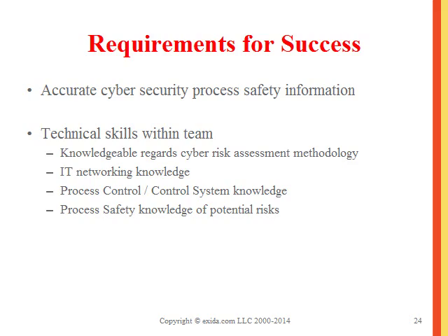So how do we make sure that we're successful in this exercise? You need good information about the process, your cybersecurity process safety information. You need to understand clearly what your hardware is, what possible entry points for threats, where vulnerabilities can be injected into the system. And you also want to make sure that your technical team that's doing this analysis has good knowledge of cyber risk assessment methodologies, what we're talking about here, any IT networking, and again, knowledge about your control systems and specifically your safety system, your associated safety system.